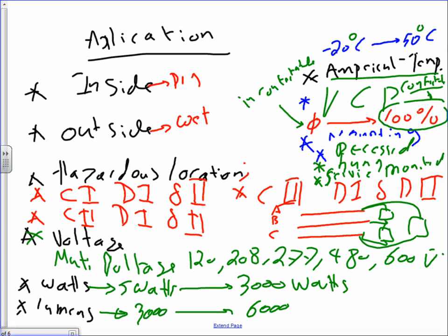The second major decision is hazardous location. Are we in a location where there are explosive gases and vapors that we need to pay attention to? If yes, you are moving completely into a different type of fixture. If no, your only division is wet, damp, or dry. Can I have thumbs up, Chad, on that? Okay, now, hazardous location: Class 1, Div 1 or Div 2.